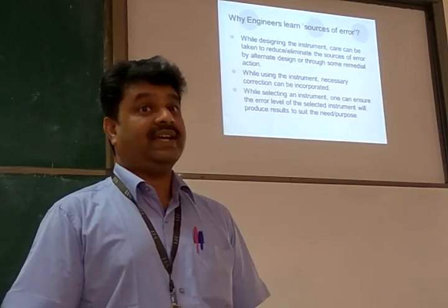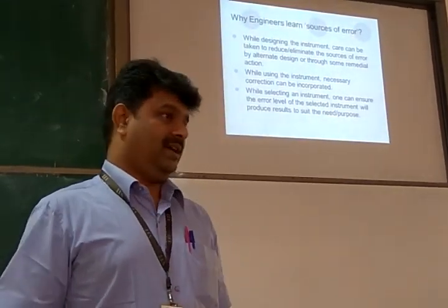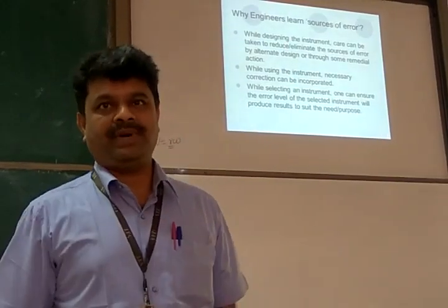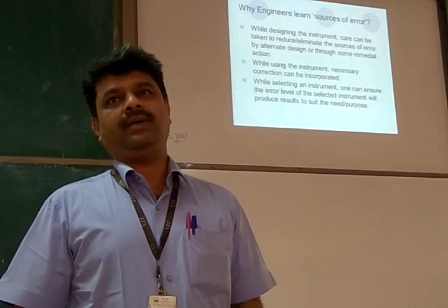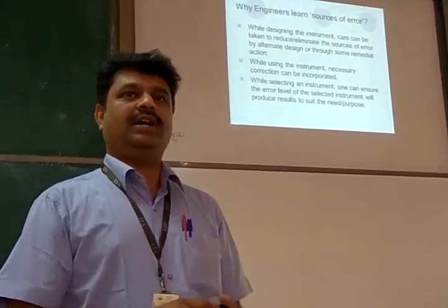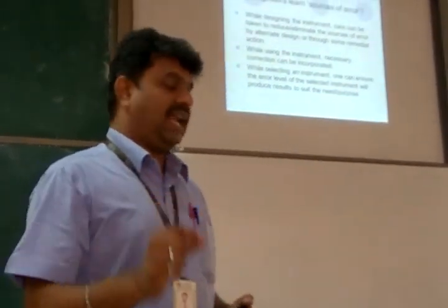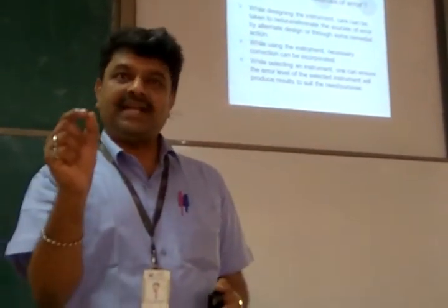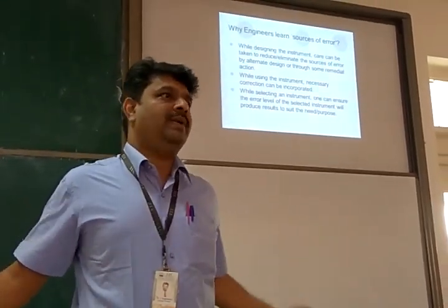Okay. That is at the designing stage, if I am the designer of that particular instrument. No, I am not a designer, I am a user in a particular company. I am now buying an instrument. If I am buying an instrument, if I know what are all the sources of error and the remedial action well in advance, I will be able to select the right instrument which will get affected less by the parameters that my environment has in my company.